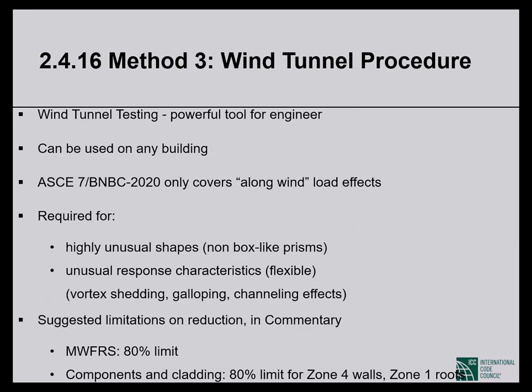Most of the time, any building in Chicago exceeding maybe 20 stories, which isn't much, is designed based on wind tunnel testing. Simply because you get to design the building for lower pressure than you will calculate out of ASCE 7. It is a fact. Okay.